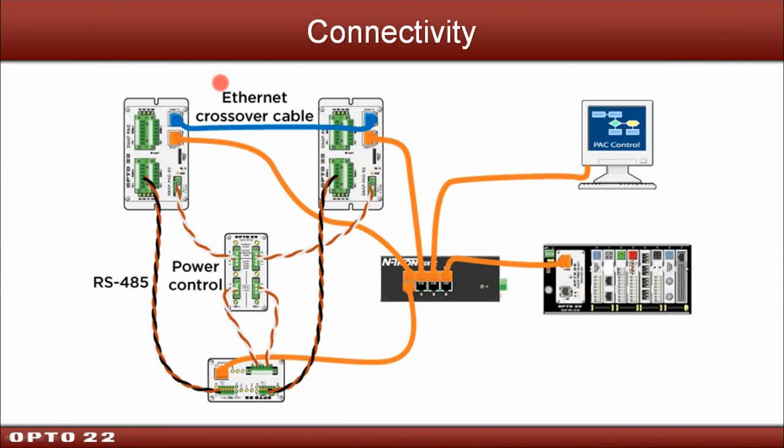They're not arbitrary placement. Again, what happens is you have a sync block that indicates the end of a transaction, then the beginning of a new transaction with the next block that does a write to variables or a write to outputs of I/O. So you could have a lot of other blocks that do various things that don't write to I/O or write to variables. The transaction hasn't started yet.